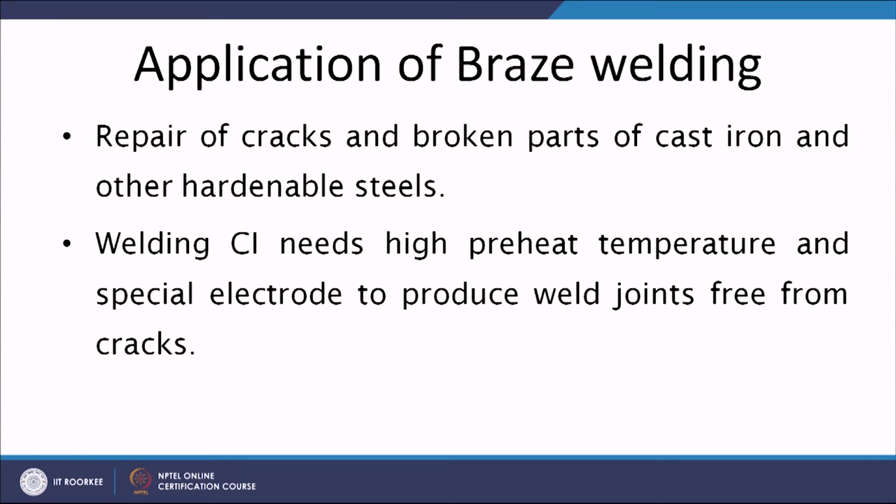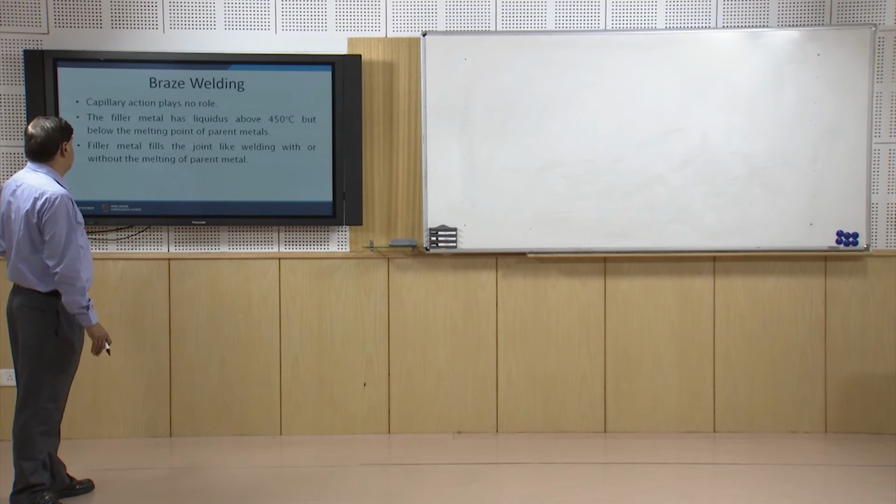In case of cast iron, if repair work is needed, then preheating is required to avoid the further cracking tendency.